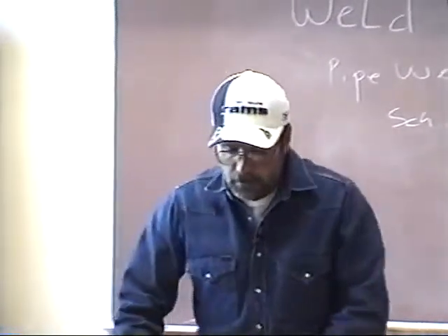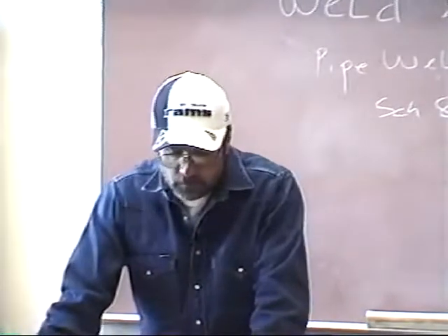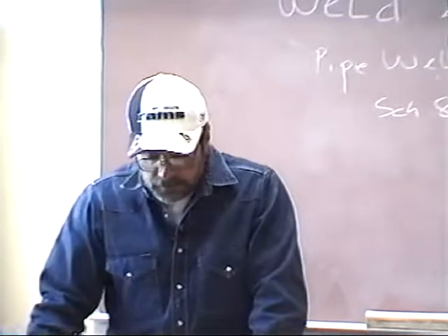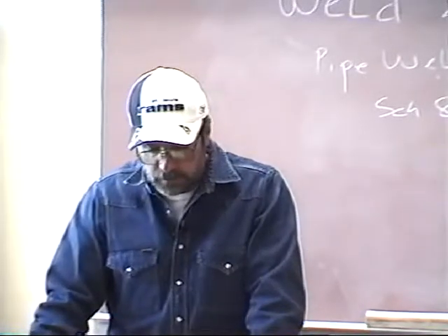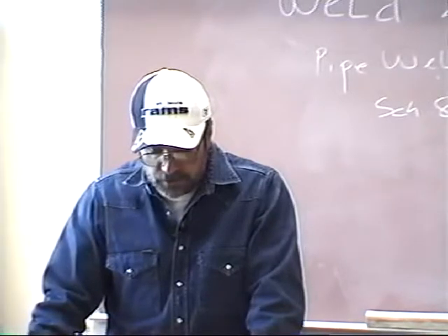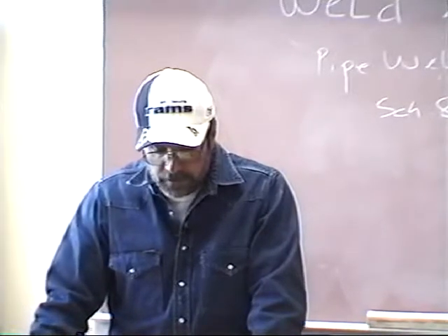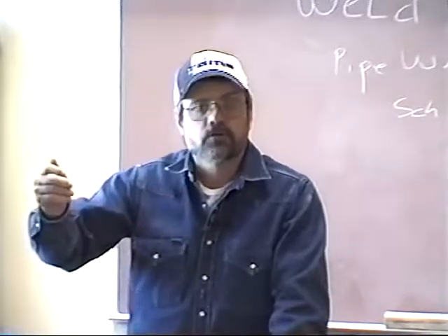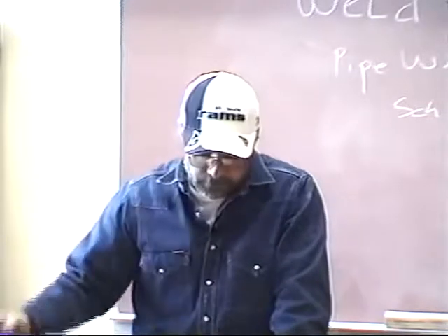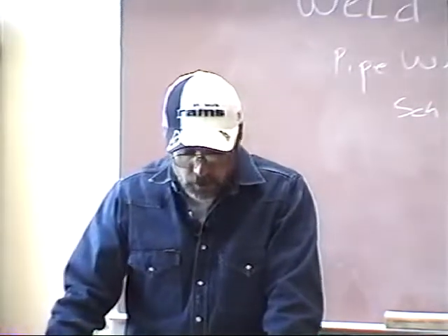Turning over to page 20, the distribution of heat in the weld zone is affected by the welding technique. While welding, the electrode and the arc are sometimes deliberately moved in and out of the puddle of molten metal in a uniform pattern to reduce the temperature of the molten metal and to preheat the metal ahead of the weld. So if you're using your whipping technique, we're controlling the heat in the puddle, but we're also preheating ahead of where we're going. This technique is called whipping.